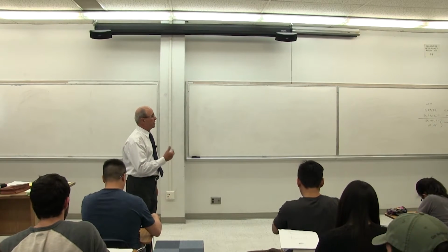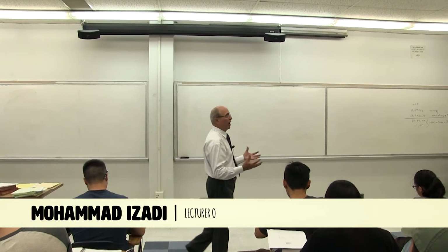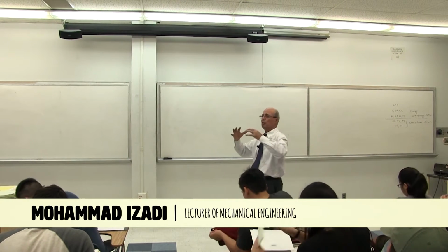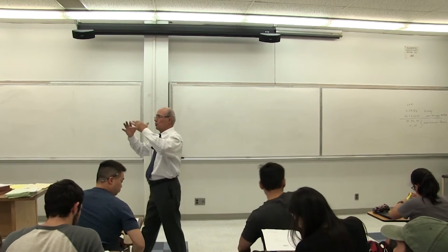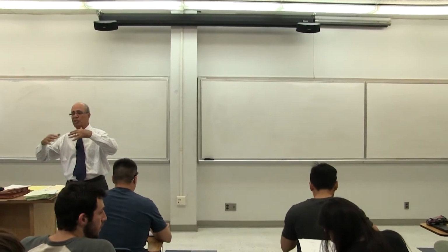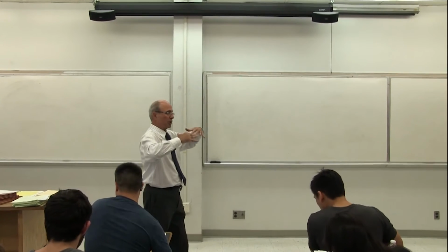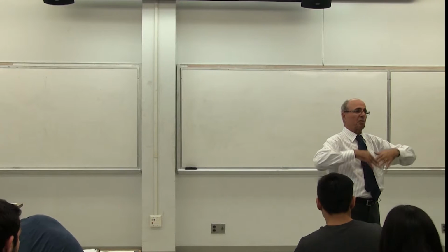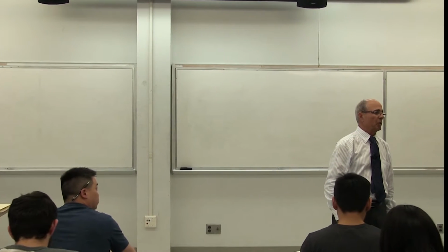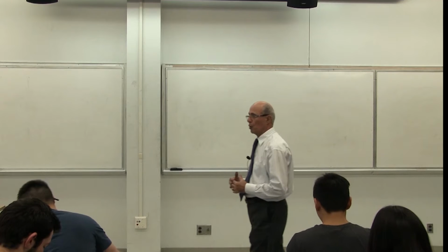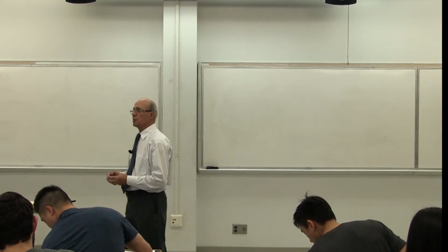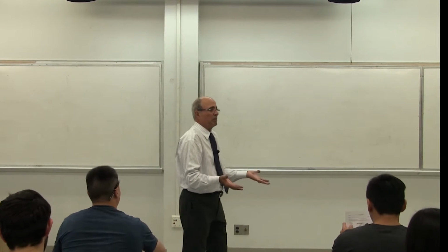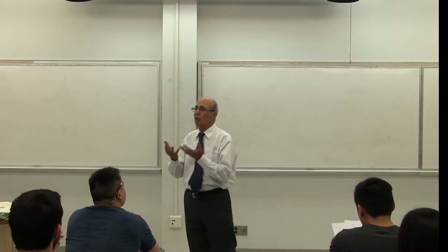Strain energy is the energy stored when you load a structure and the structure undergoes deformation, like a beam. You put a load on it, whatever it is, a uniform load or a single load, and the structure goes down. As soon as you remove the load, the structure goes back to its original position. That means that during the loading, some energy is stored in the system, because taking the beam back to its original location requires some work.